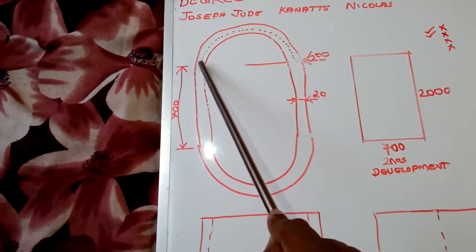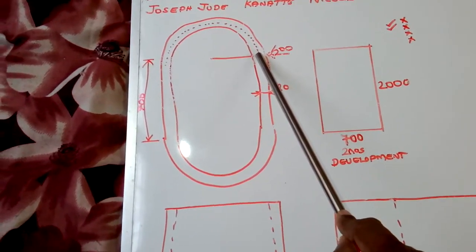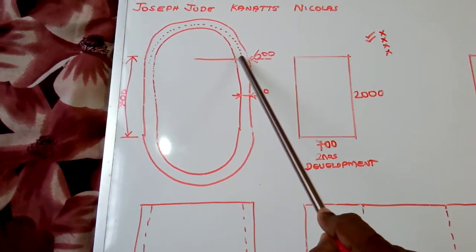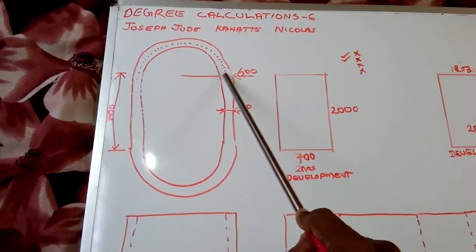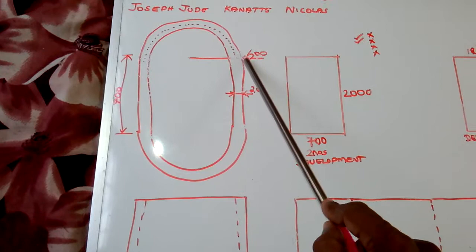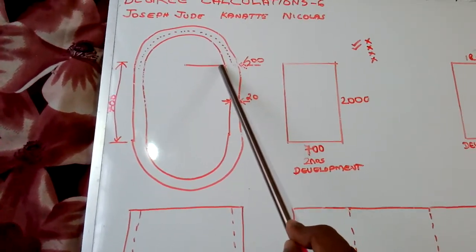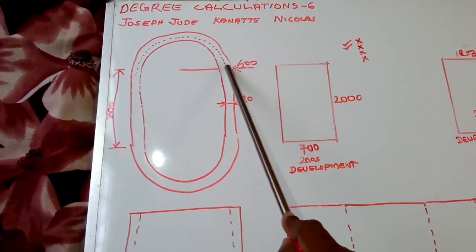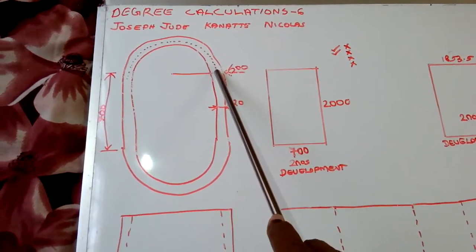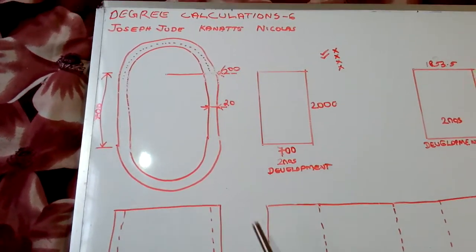Here I have indicated a dotted line. From dotted line to dotted line is the medium diameter. This medium diameter won't change when we roll, but the major diameter will increase and the minor diameter will decrease. So the medium diameter won't change when we bend or roll, so we have to use the medium diameter.